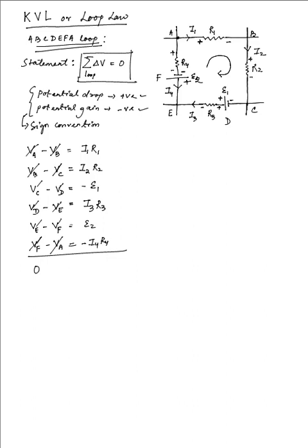That is what the law says, that the net potential difference across a closed loop has to be equal to zero. Now consider the right hand side of the equation. With all those things added as well, what we end up with is I1 R1 plus I2 R2 plus I3 R3. Let me write the I4 R4 term as well, but that is in minus, so minus I4 R4. And we have the EMFs then, that is minus E1 plus E2.